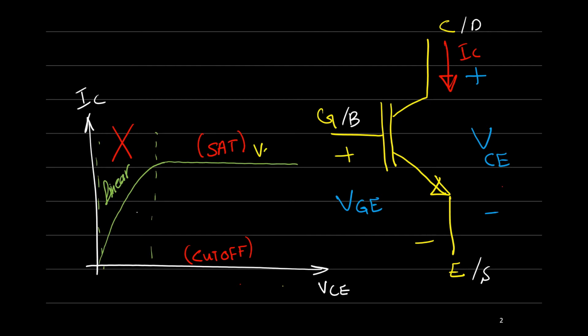When the signal on the gate is 5 volts, which is a small signal compared to the power side, this means the transistor is on, and the current flows inside this transistor, so it will be as a short circuit. When the VGE is 0 volts, then the transistor will be considered off, which means the transistor acts as an open circuit.